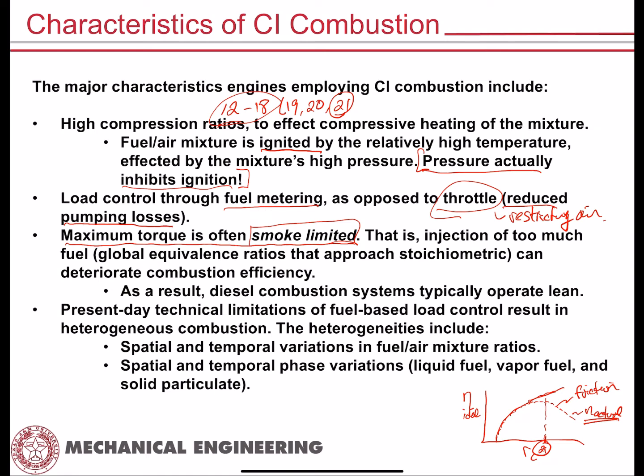So if you want to make more torque, what do you do? You increase the amount of fuel you inject. Now you increase the amount of fuel you inject to 0.7, okay? And then you increase it to, say, 0.8. And what happens? Well, as you inject more and more fuel, now you're adding more and more time to the physical processes that have to take place before that fuel can ignite, okay?